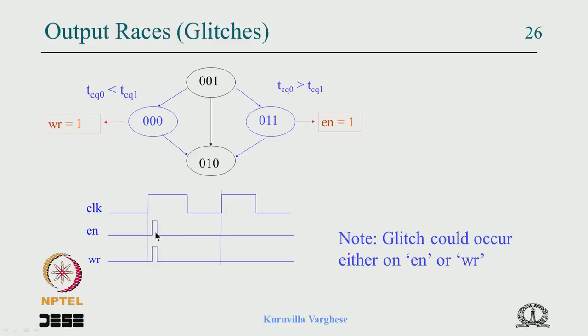If this is used to enable a counter, it does not matter, because when you enable something using clock gating or a recirculating mux, nothing is going to happen unless the enable stretches over the clock edge. So in a synchronous case it may not create a problem, but we don't know how this is used. Maybe this is used asynchronously to increment a counter, or this write is going to an asynchronous memory as a write pulse.